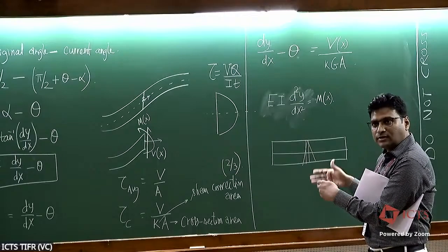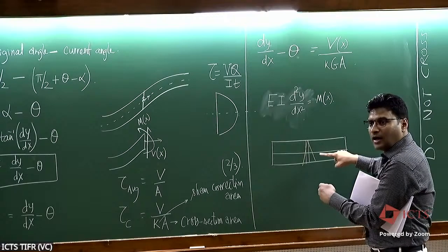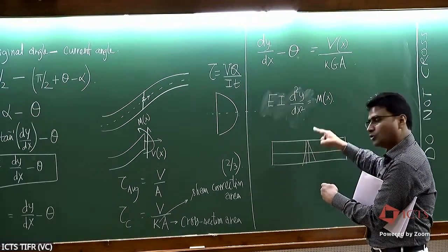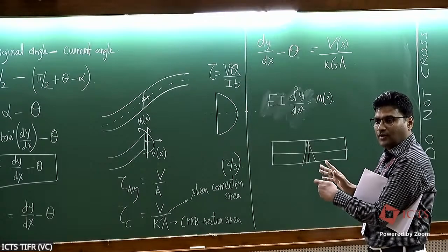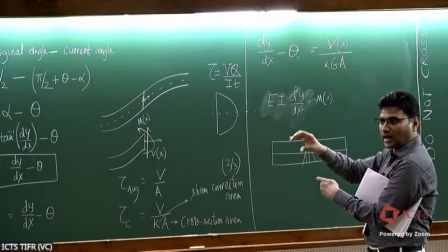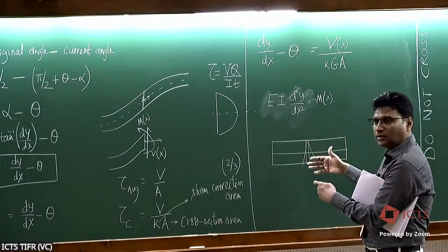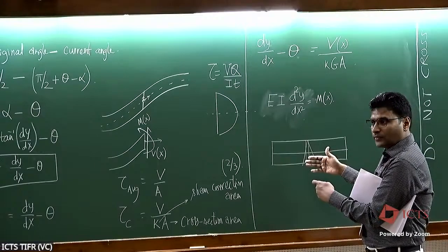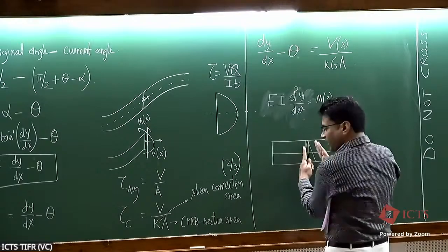So that description is not going to come through the center line unless the center line and the cross-section normal are aligned. Then it's a different thing. But in this theory, the center line tangent and cross-section normal are not aligned. So you have to independently look at the cross-section normal, and then you have to see how theta is varying.